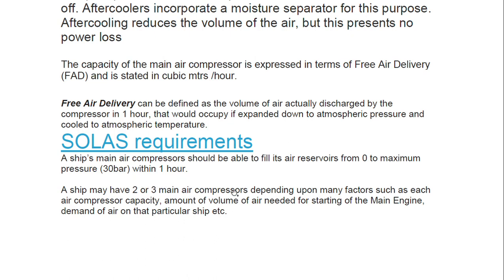So within 1 hour it must be able to fill the reservoir, that is the air bottle, from 0 to maximum 30 bar. A ship may have 2 or 3 main air compressors, as I told you earlier, depending upon many factors such as each air compressor's capacity, the volume of air needed for starting of the main engine, demand of air on that particular ship, etc.